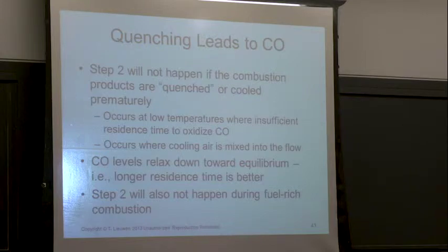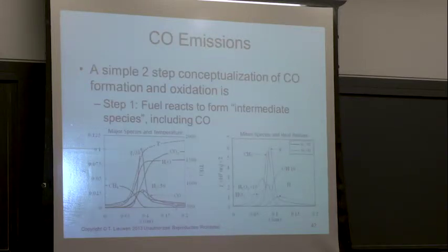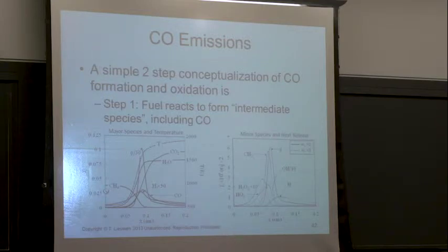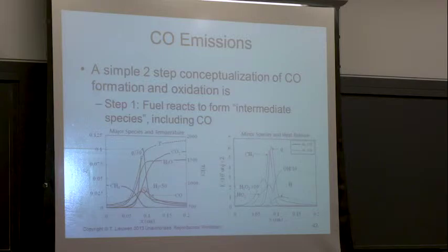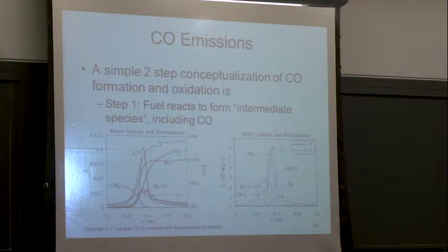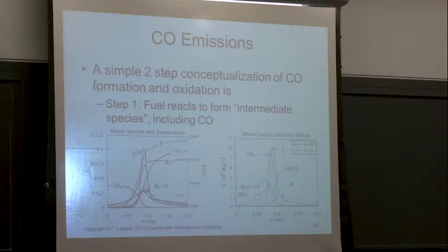So you're forming a massive amount of CO in the flame. Look at this number. This is CO. For this particular example, this would be about 27,000 parts per million of CO. You know, at 200, 300 parts per million of CO, you're going to get a massive headache and die in an hour or something like that. At 1,000 ppm of CO, you're going to be throwing up and die really fast. So in the flame, you've got about 27,000 parts per million of CO.